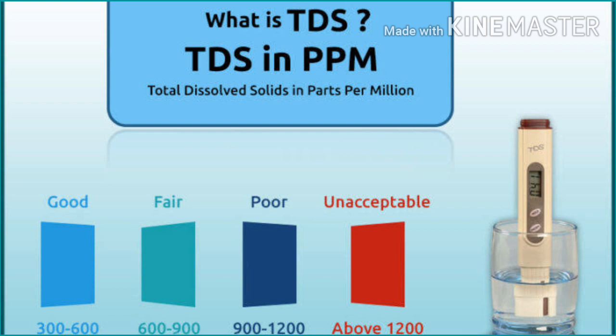Substances that are considered dangerous in high amounts are listed with a maximum acceptable concentration in the guidelines for drinking water quality. However, substances that are not considered dangerous at high levels, such as TDS, are given objective guidelines: 500 milligrams per liter, which is the same as 500 parts per million. However, since the guideline is not enforceable, each province is free to choose whether or not to follow it. For high concentrations of TDS, the province has chosen not to follow the guideline of 500 parts per million and to implement its own guideline of 1500 parts per million.